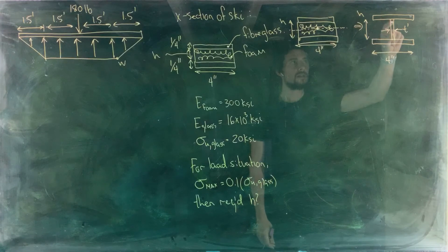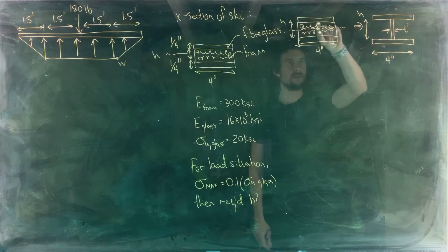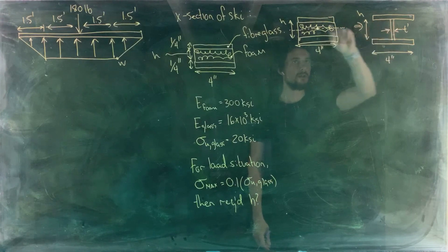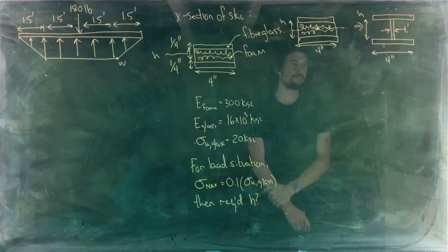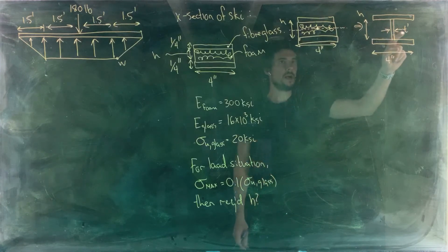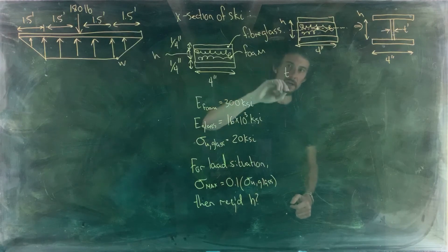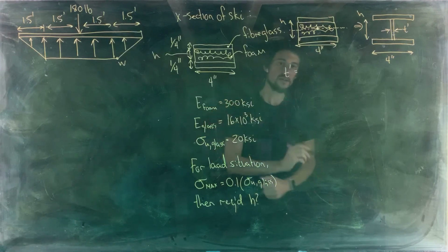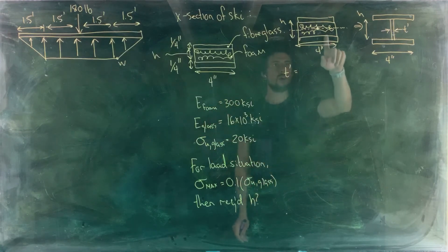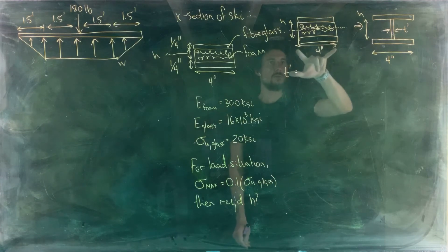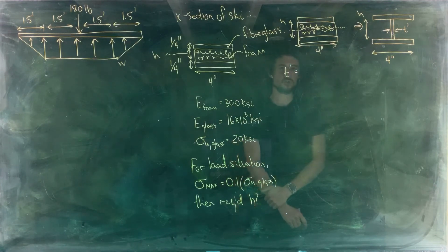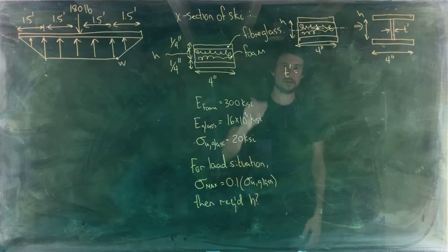Because the fiberglass is stiffer than the foam, a very small piece of fiberglass would deform equivalently under the influence of a bending moment to that foam. T prime is really easy to find, because T prime is just the ratio of the two moduli of elasticity multiplied by the original thickness here.